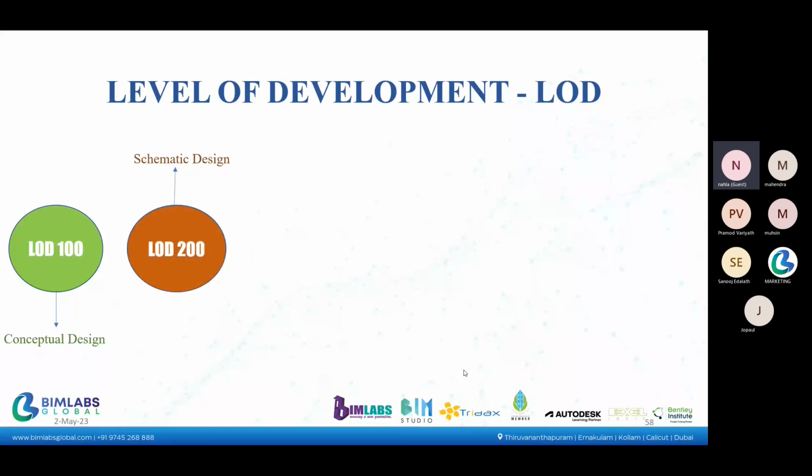Then comes the schematic design, LOD 200. LOD 200 means a schematic design. Schematic design means much more detail. When compared to LOD 100, we have much more detail in the schematic design. For example, approximate quantity, size, and shape can all be incorporated in the schematic design.